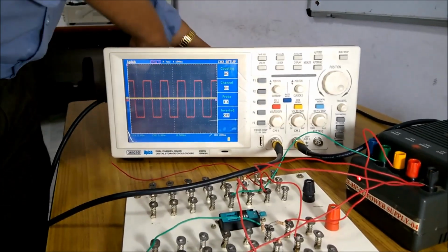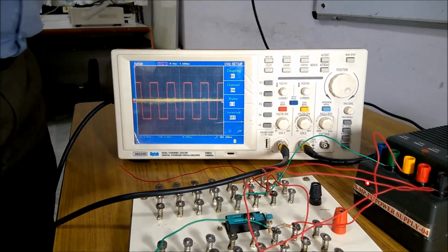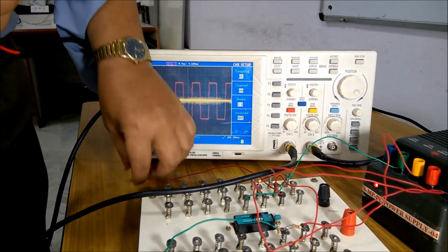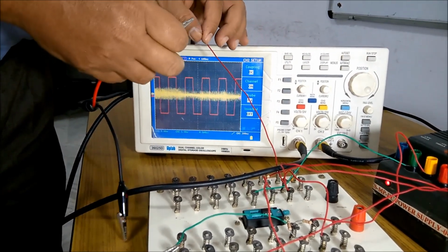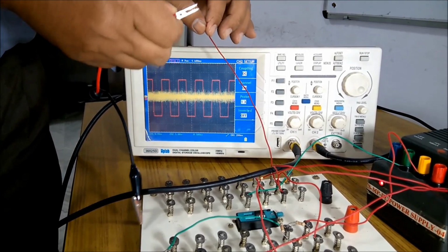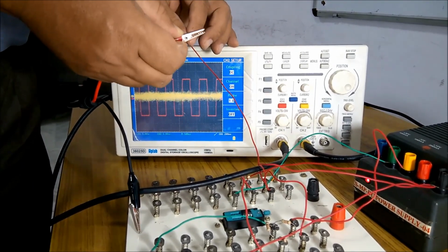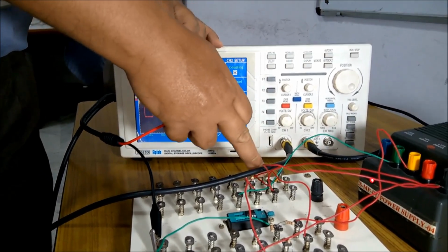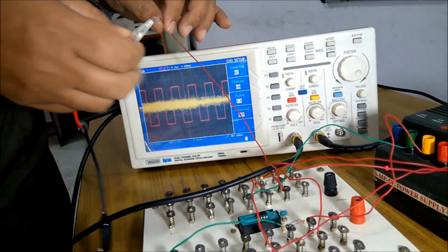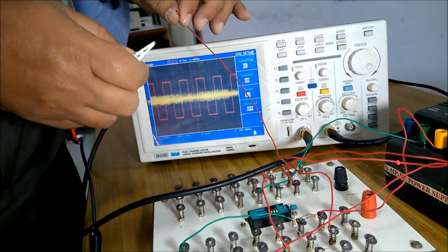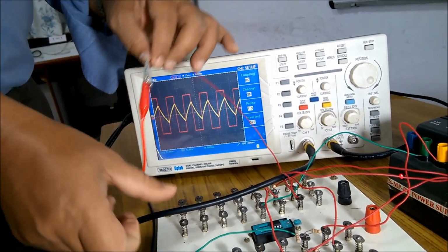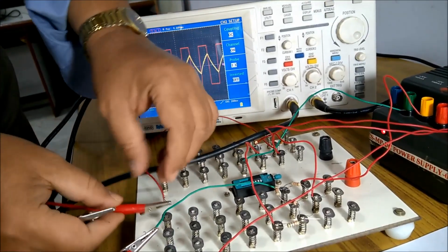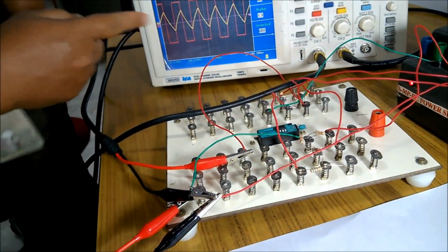This is channel number 2. Again, the red one is to be connected to the capacitor plate which is connected to pin 2, and that is the point where you should be careful. You should not connect the channel number 2 red terminal to the ground plate, because the ground plate will give 0 voltage. You have to connect to where the capacitor plate is connected to pin number 2. That point only you should connect the red one to. After connecting it, the black one should be connected to the common ground. You can see then we are getting a capacitor waveform.